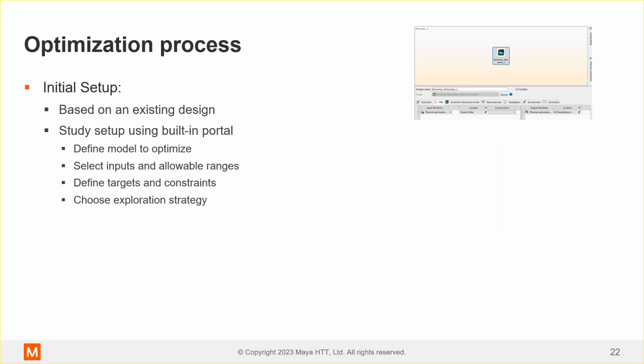So to set up the optimization process, I guess just to go over it fairly quickly for you guys, since we've talked about the design variables that we're concerned with. HEEDS has a MotorSolve portal. That means that HEEDS knows how to read in MotorSolve save files. It knows how to modify them, how to read out results, and how to basically rerun analyses. So using the built-in portal, it's really easy.